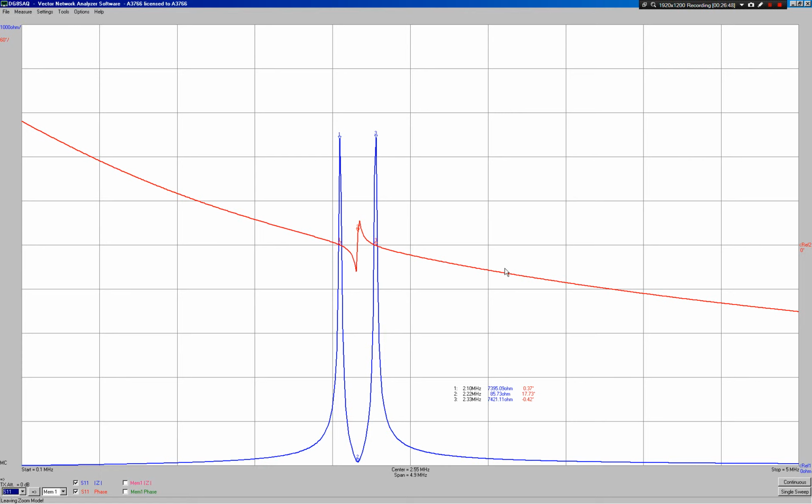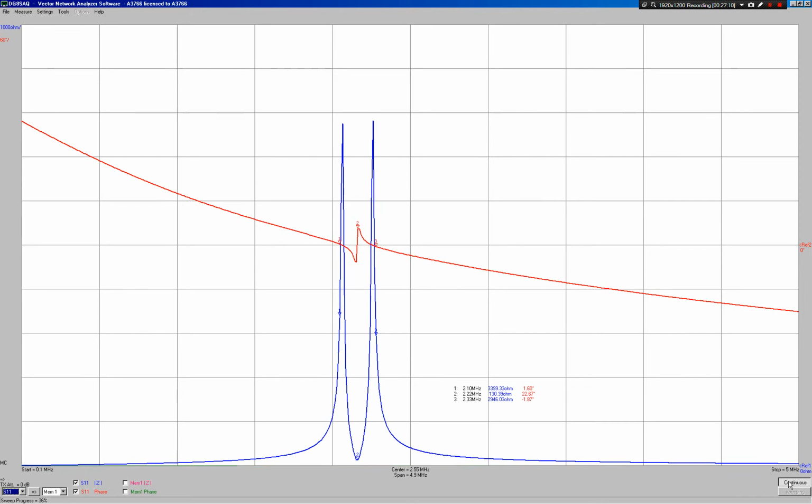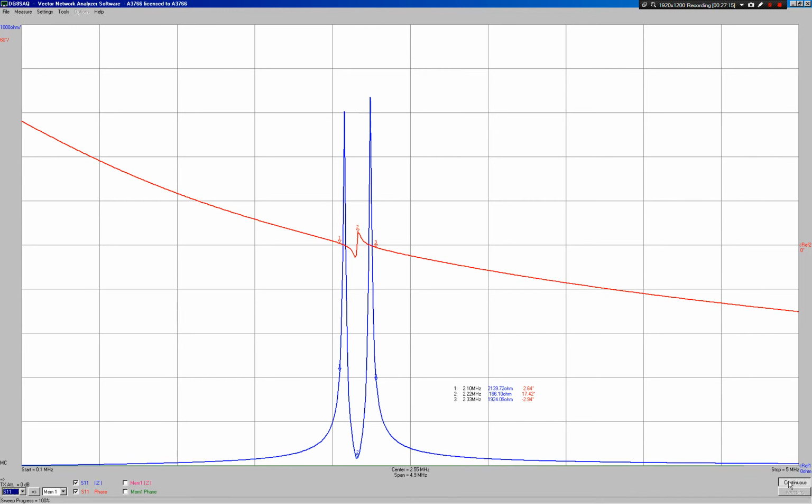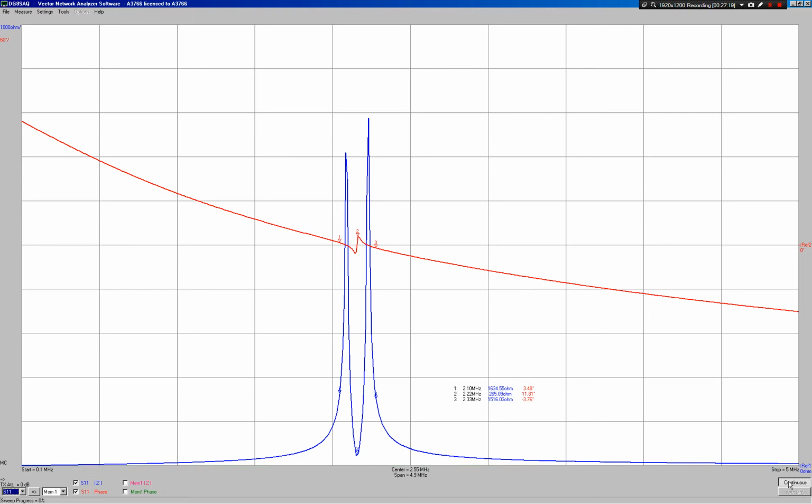Remove the LCR meter. And we'll just take another scan, make sure we're still looking balanced. Yep, that's good. Okay, so I'm going to put it back in continuous, and we're going to continue now moving the secondary away. Collapsing still. Balance is okay. Still sliding away the secondary. Let's just check the distance now. 30 centimeters.